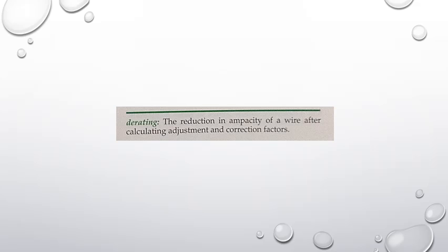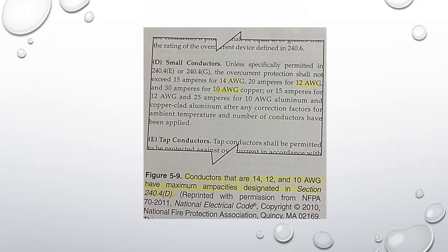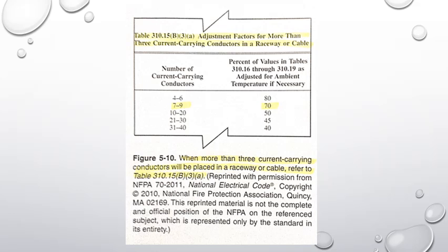Multiple conductor ampacity adjustment factors. The 3 conditions shown above Table 310.15(B)(16) are required because the ampacity rating of a conductor will decrease as the temperature of the conductor increases. Having multiple current carrying conductors in one raceway or cable increases the temperature of those conductors.